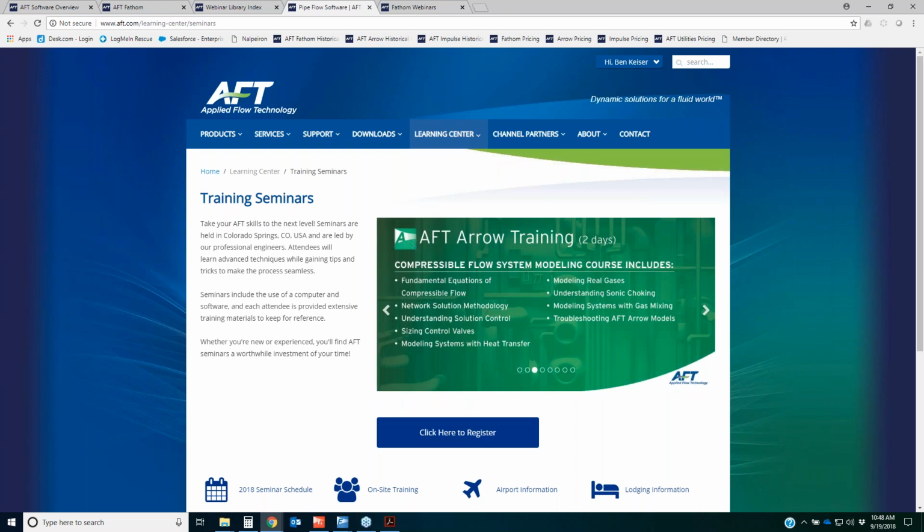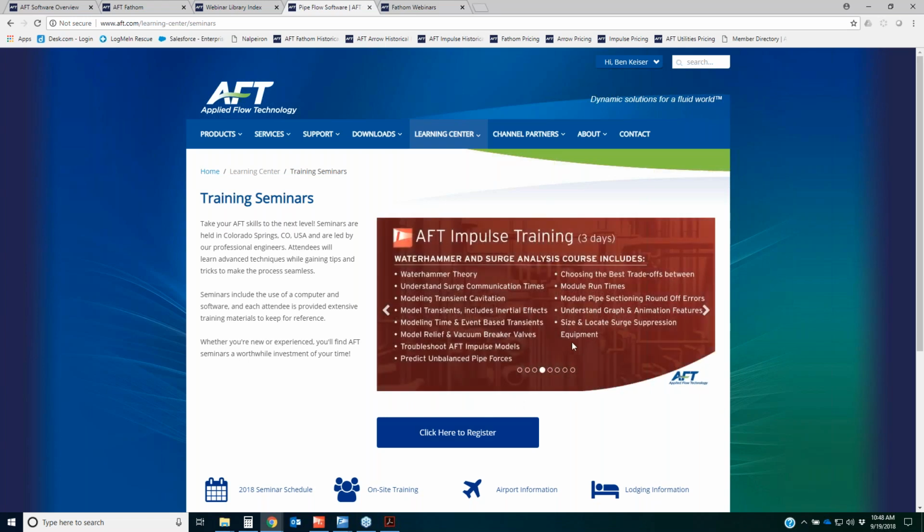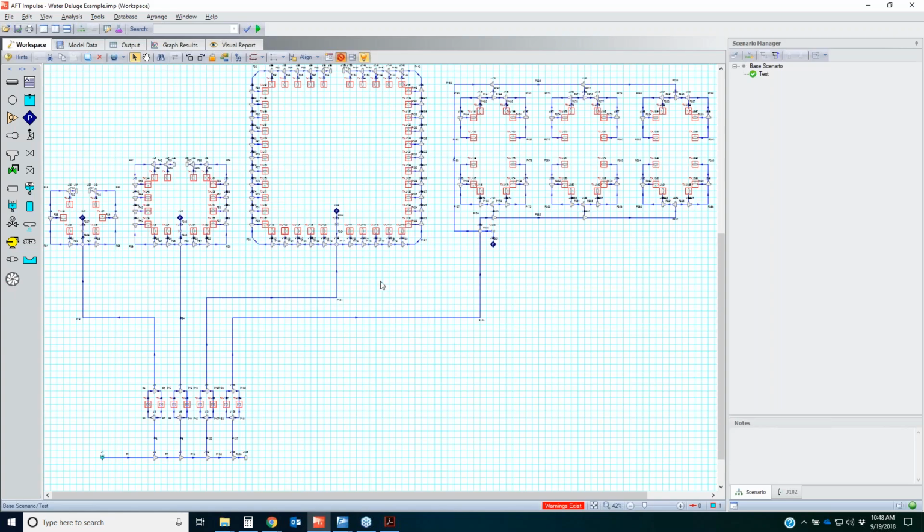because waterhammer modeling is very much a gray area. It's not black and white. It takes a lot of careful interpretation to really figure out what's going on. That's where you have to learn the tips and tricks on how to model this system appropriately to get an initial solution. So I've already run the model and I've got results. Basically, long story short, everything's off, and then we're turning everything on very quickly, and we're flooding the launch pad with tons of water.